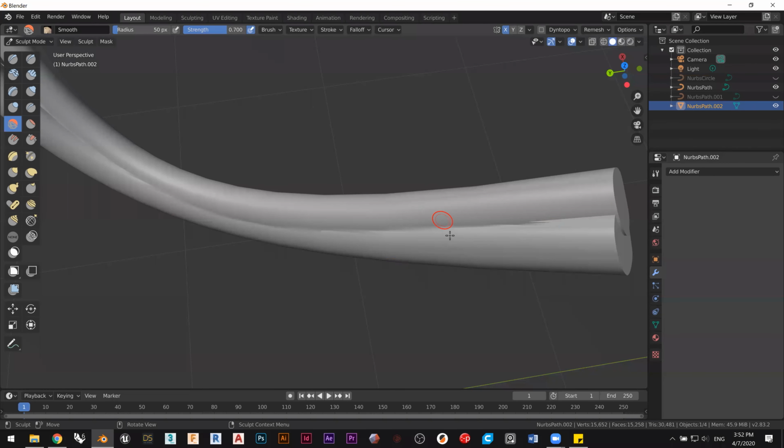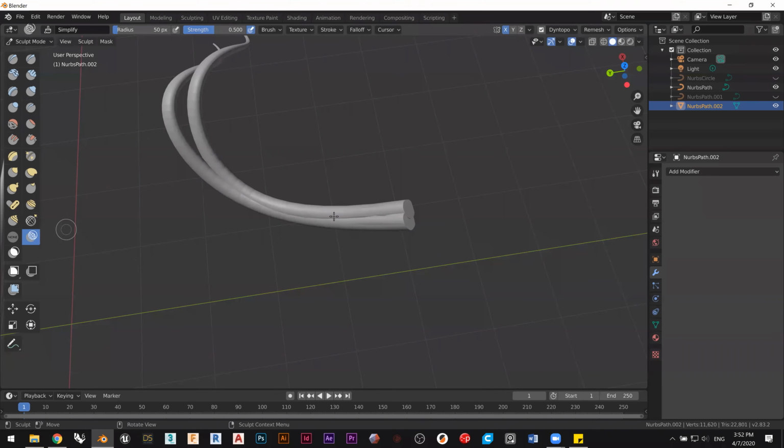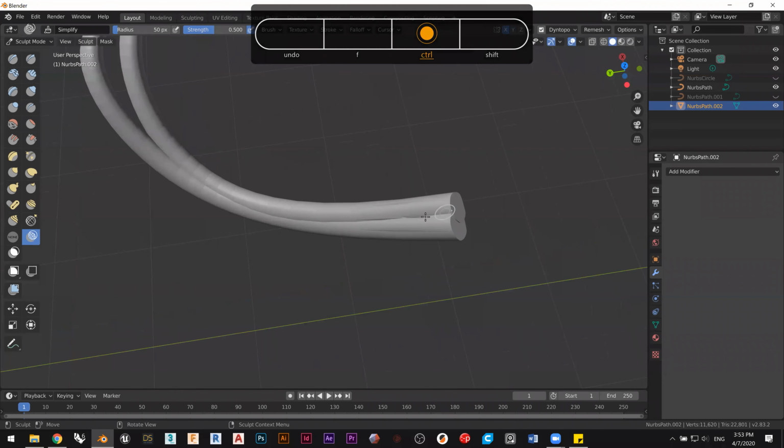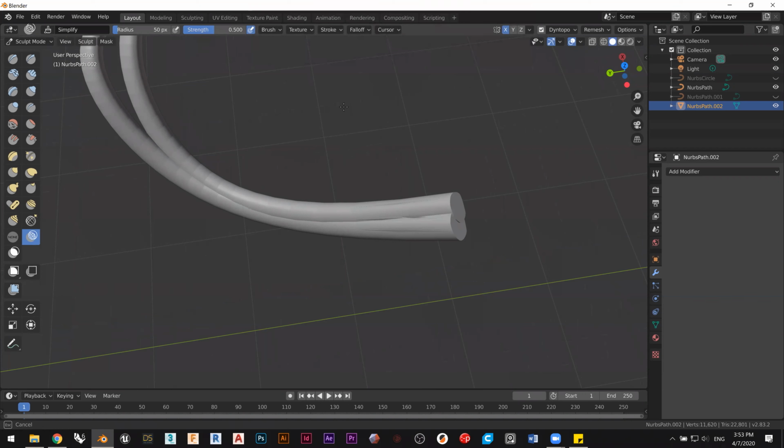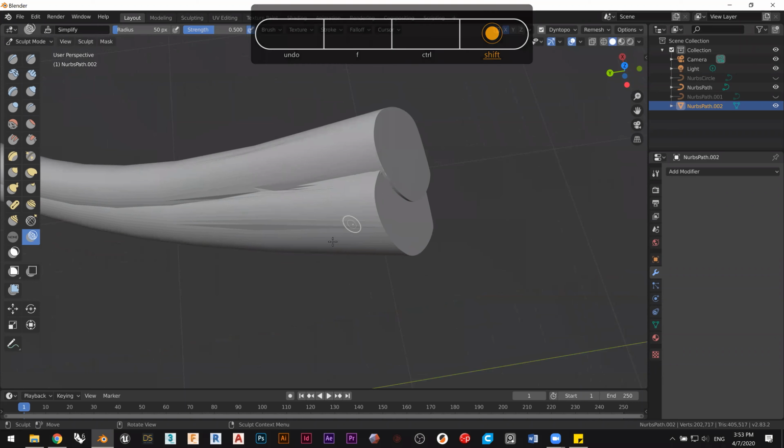If this happens, if the smoothing is weird, don't forget to go to create dynamic topology from it. Where is it? No, not remesh. Dynamic topology, brush detail. I don't know, I'll use like 15%. And first use simplify, like hit it with the simplify around the seam. That was probably not a good idea. Let me just see what simplify did with it.